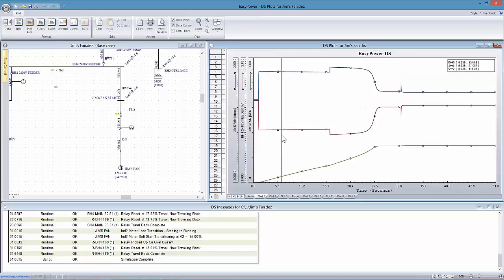If I go back and look at my motor, so this is specifically the fan current, the voltage, and then the RPM on the motor. You can see that the motor is drawing 1,300 amps, again at a different voltage than our main plant. We're getting the speed up to, looks like 850 RPM.